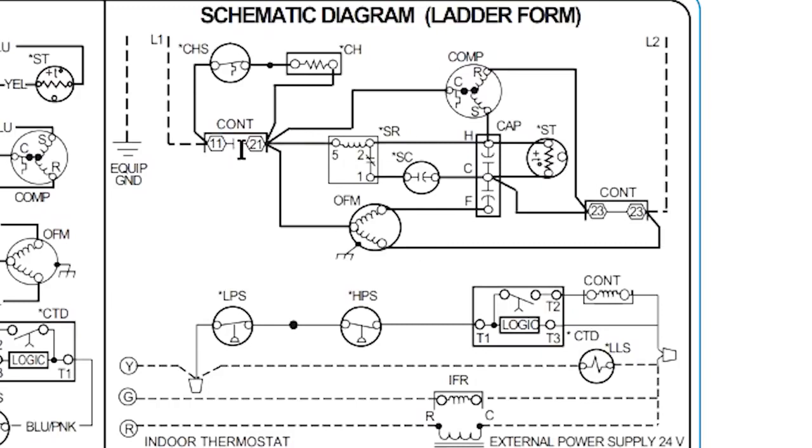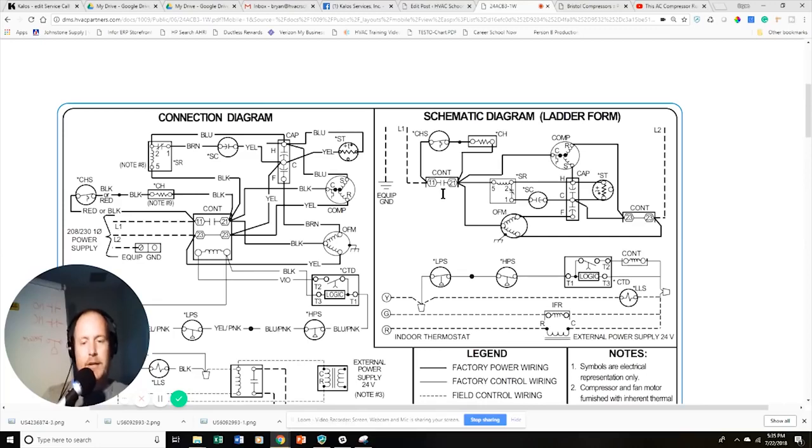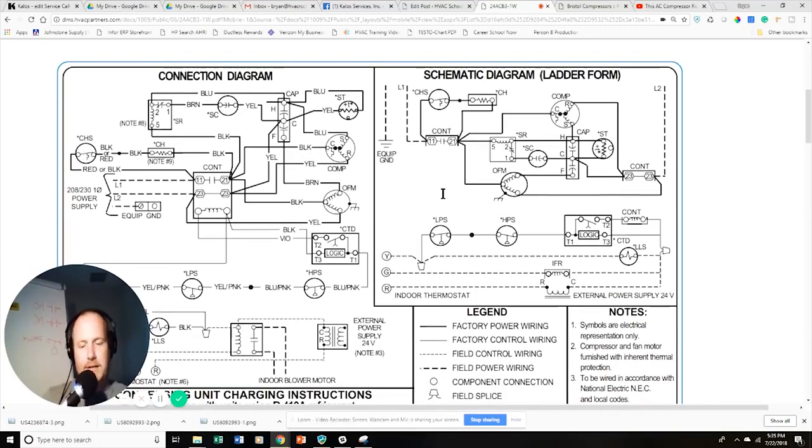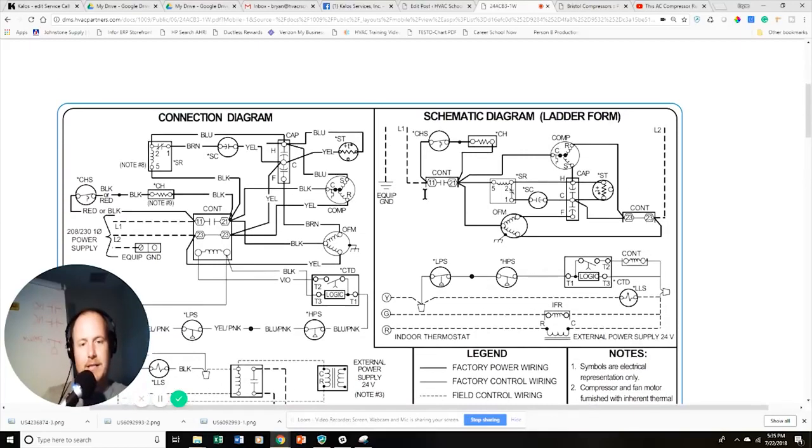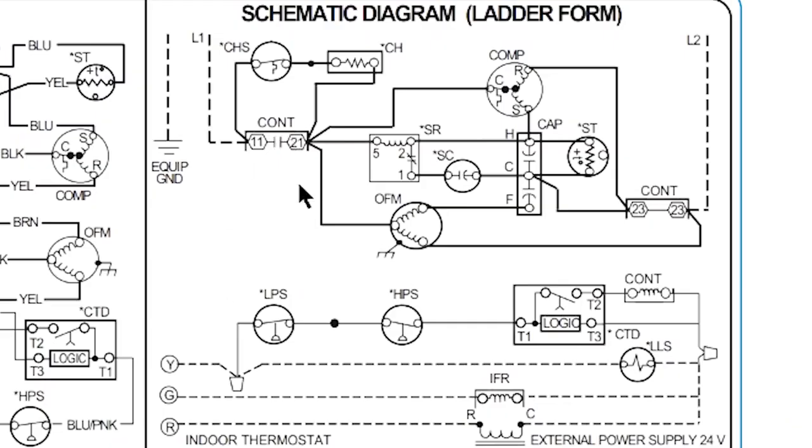All right, so now we go through this contactor. This is a normally open contact. How can you know? Because if you look at it, you can see that there's a gap in between these two contact points. This is sort of a universal symbol for a contact. I could show you the symbol separately on its own sheet, but I'm using a real diagram that you're going to see in the field, and I'm just going to teach you what all these mean as we go. So this is a contact. This is a normally open contact because it doesn't have a slash through it. If it were to have a slash through it, then that would be normally closed.